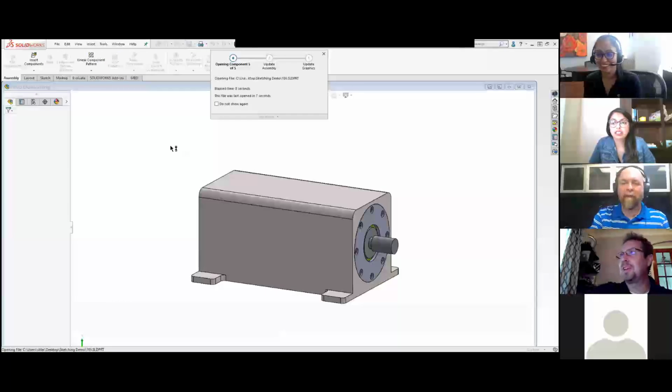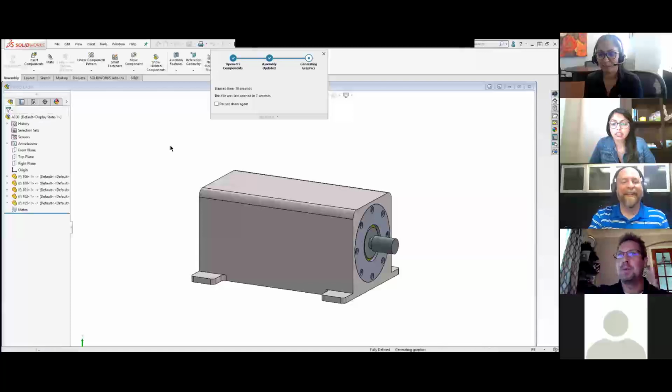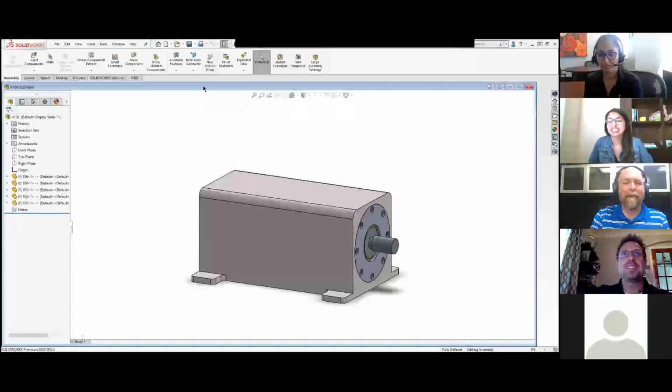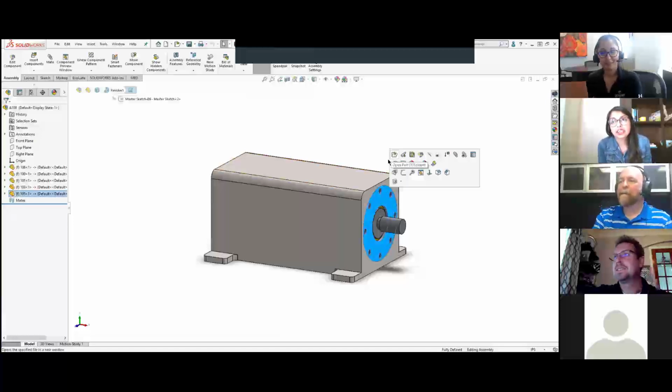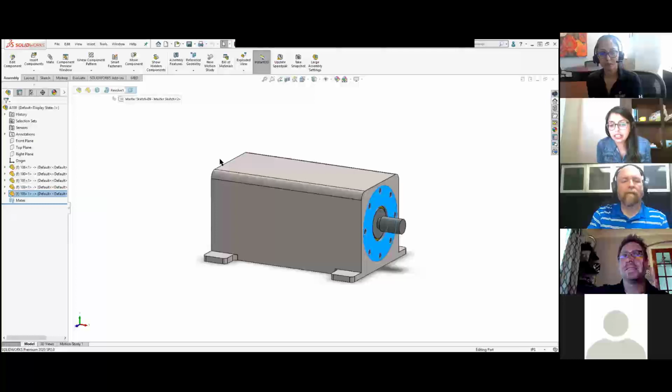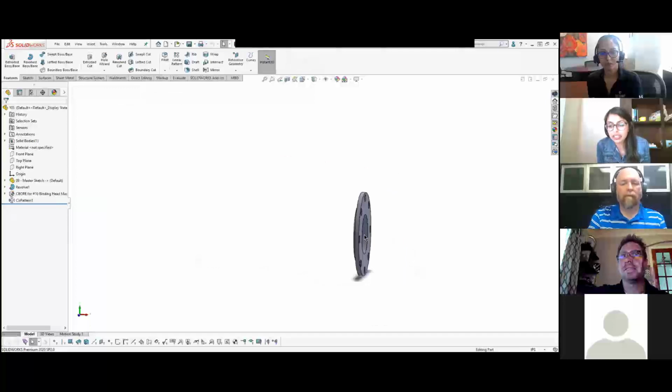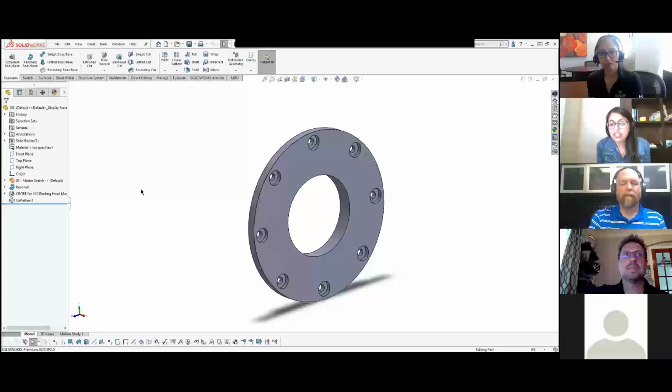Yeah, and sometimes you don't know. You got to wait till the guy comes back from the shop to do the dimensions. And well, you make up something too. Anyway. Well, and once you have a part that's got errors in the sketch, and then you insert that into an assembly and insert that assembly into another assembly, the issue can compound. So we always recommend you have fully defined sketches, but there may be certain instances you can't, and I'm not a fan of fixing geometry blindly, but sometimes you can do that to get around the issue.